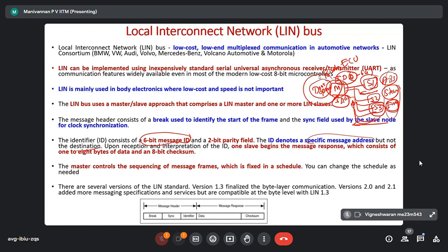Another thing I also told you, do you remember? When you send a message on the CAN bus, I told you there are 3 devices connected by a CAN bus, right? So 1, 2, 3. This has ID 0, this has ID 10, this has ID 20, correct? Message ID. Now, when nobody was transmitting data, device 3 was transmitting ID 20. When nobody is transmitting, there is no competition, anybody can transmit. That is the CAN bus advantage. So ID 20 was even the lowest priority, but device 3 was able to send the data on the CAN bus.